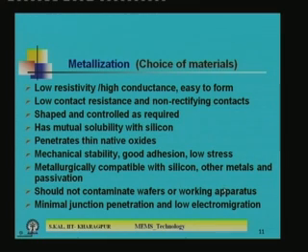So, in high speed circuit or any of the VLSI circuit, the metal lines are required only for interconnect. So, their resistance should not be incorporated. So, low resistivity should be there, that means high conductance, and easy to form. Easy to form means that metal film can easily pattern. That means there are certain metal films by lithography you cannot get the pattern. One such is, say, copper, but you have to go for certain metal film which can be easily patterned by conventional lithography and etching technique.